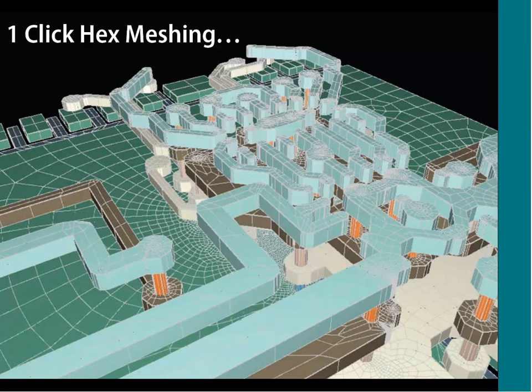And if you're using the behavioral simulator, the schematic-based simulator, you can automatically mesh a structure that way. Basically, we've tried to make it very easy to create meshes that are accurate and robust, that have the most likelihood of simulation convergence, as well as the maximum simulation speed and the best accuracy.